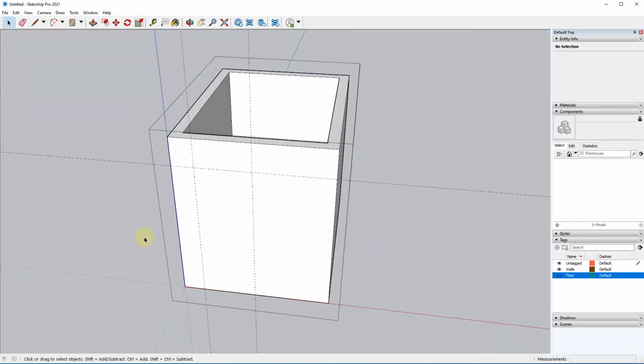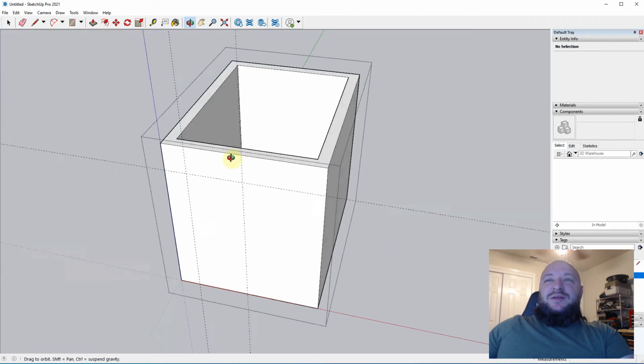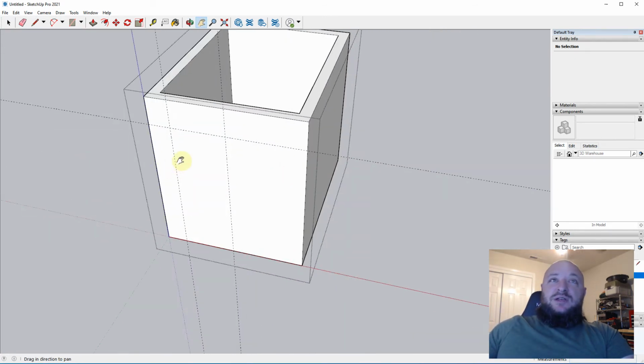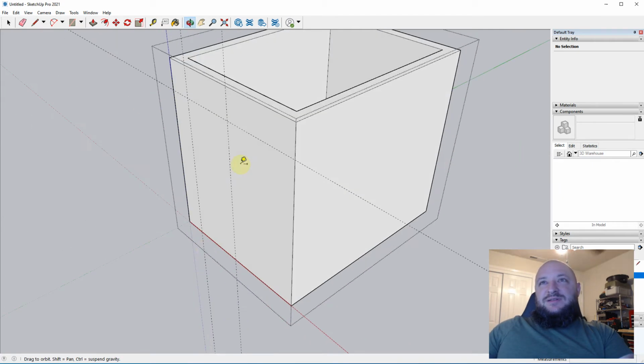So, I kind of already shot through this earlier, if you were watching. To place a hole in this wall, to actually put a door, or to cut a space out for a door, I'm going to switch over to the rectangle tool right here, and I'm going to find this intersection right here. Every once in a while I'll get a student who says, hey, I did this up 6'8", and for whatever reason, see, that one's not even quite right.